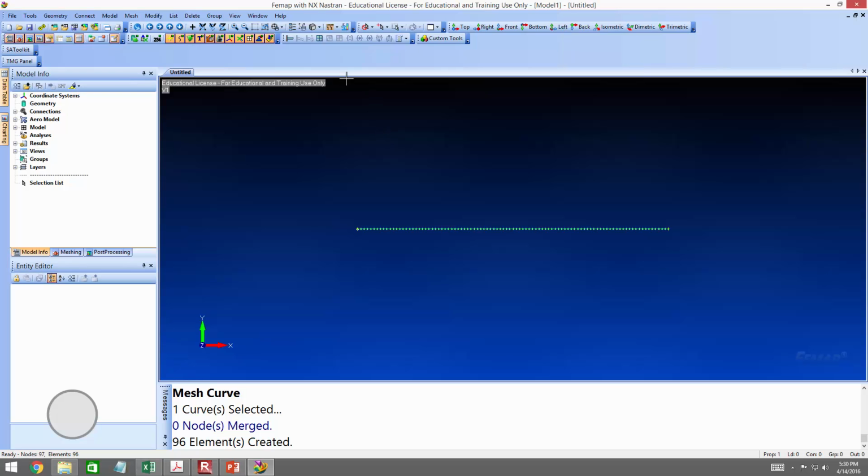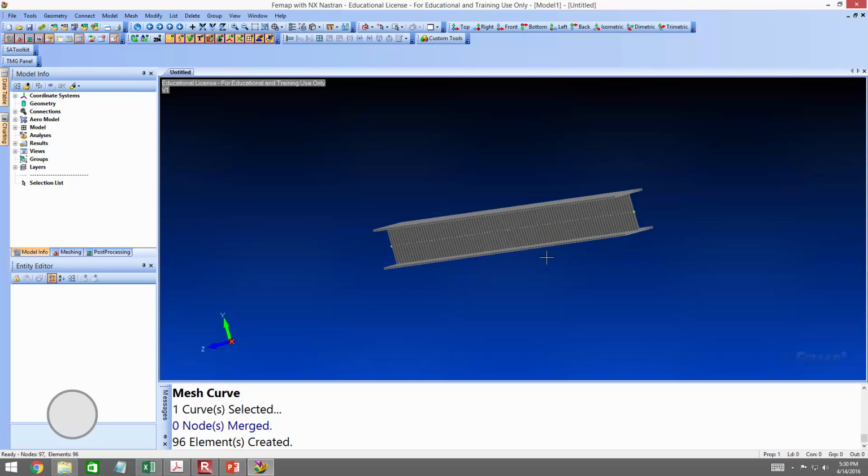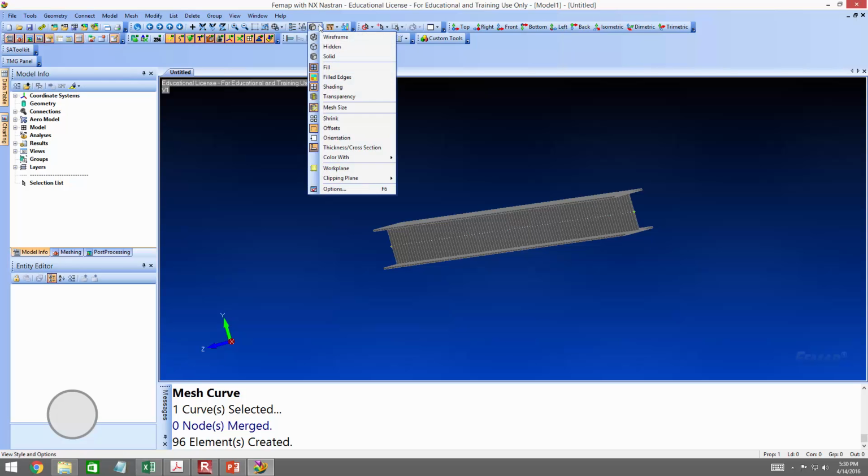All right. So if I go into isometric mode and I say, all right, I want to see what the cross-section looks like. Remember, you've got that view style, the little gray cube up top. We say, all right, show me the thickness or the cross-section. You should have something that looks like that, right? Has everybody got that? Remember, it's right here. It should be a little gray cube, and it should say thickness cross-section. You can turn that on and actually see the beam. Okay, yours is good, yours is good. Okay, you good?